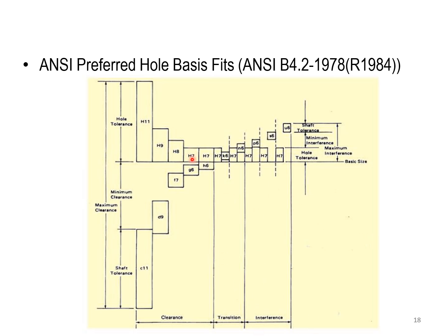You can see that the whole basic size is going to be mainly from the clearance up to the interference at the H7. Now, if I have the shaft as anything like the small letter f7 or g6 or h6, that means I'm on the clearance side. If I choose a k9 or k6 and n6, that means I am on the transition fit. And if I have it more than that, like p6 or x6 or u6, that means I have a full interference between both.